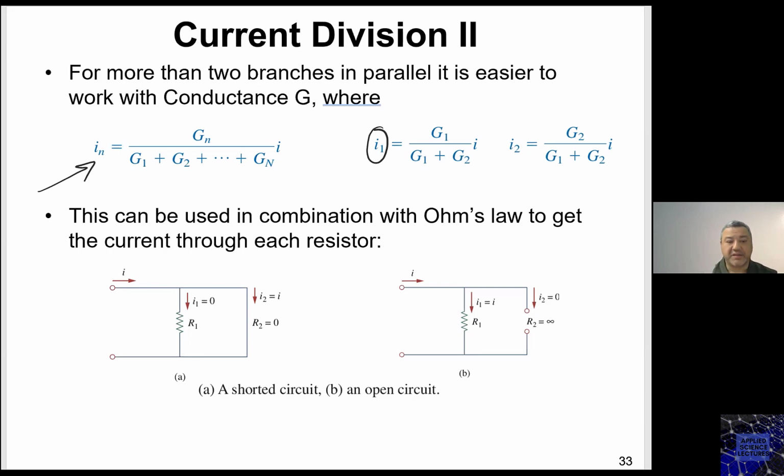All right. So you're saying, if you had 3 or 4 resistors in parallel, you can't say R equivalent is R1 times R2 times R3 times R4 over R1 plus R2 plus R3 plus R4. No, you can't do that with more than 2.